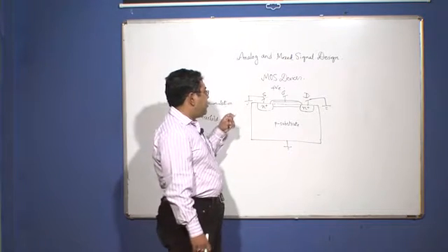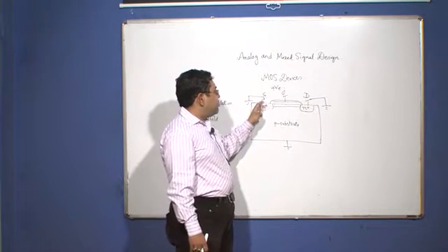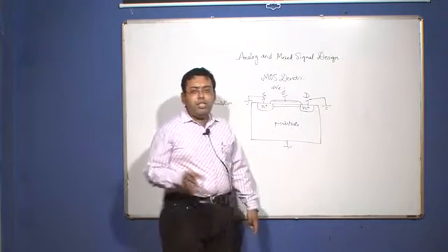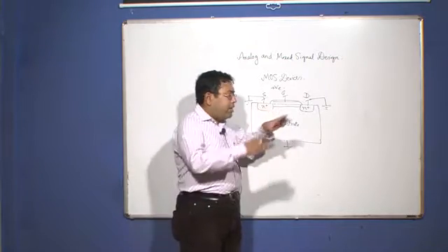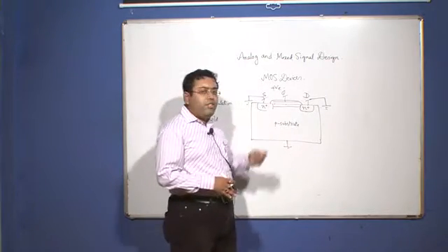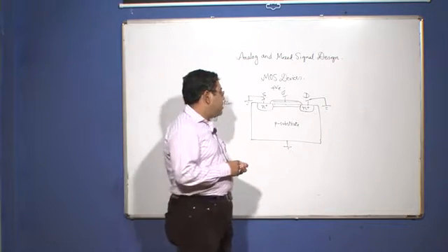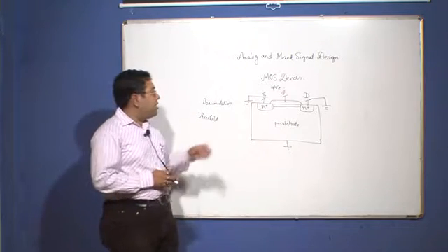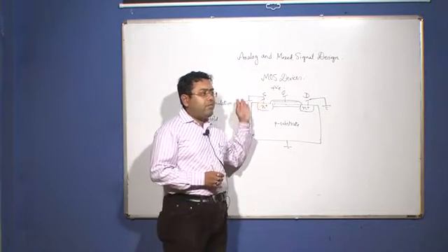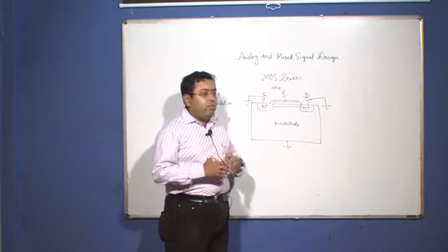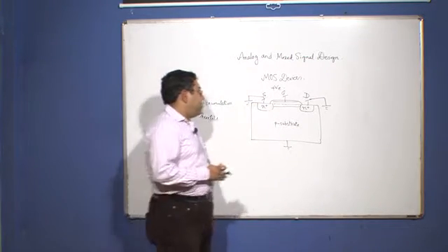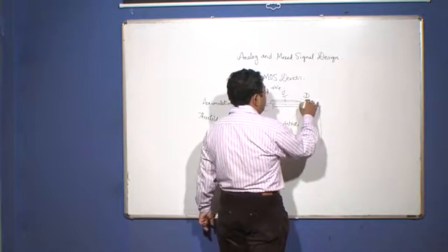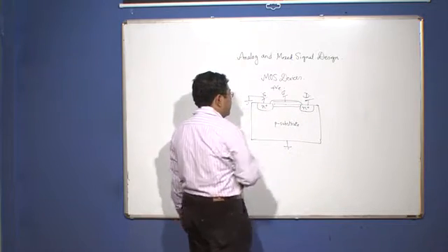Now, if you further increase the positive voltage, you will find that a stream of electrons rush from the source and drain and accumulate in the interfacial layer between the oxide and the substrate, and you find a sheet of electrons is formed at the interfacial layer between the oxide and the substrate. Now, this sheet of electrons will, however, not flow because there is no electric field being set up across the substrate to enable a drift of electrons. So, now if you want to have this sheet of electrons to move, you have to maintain a potential difference between the drain and the source.